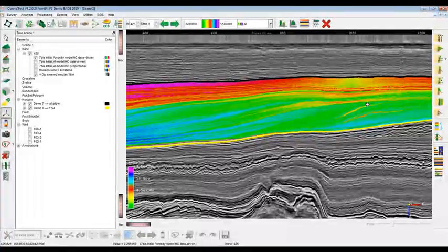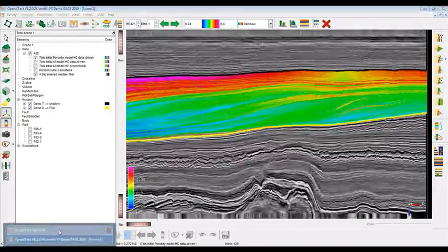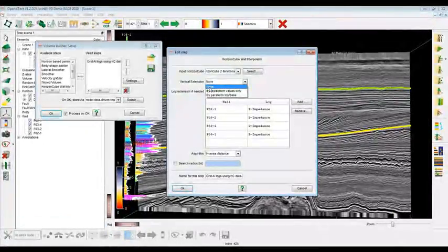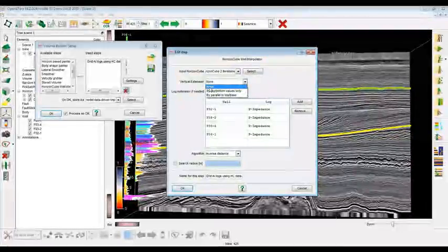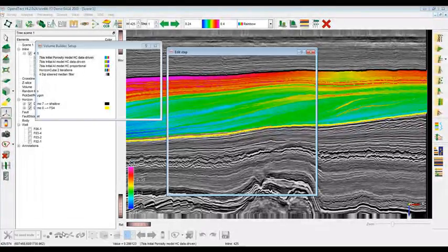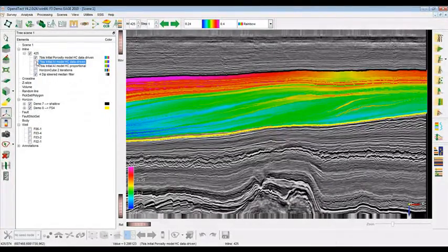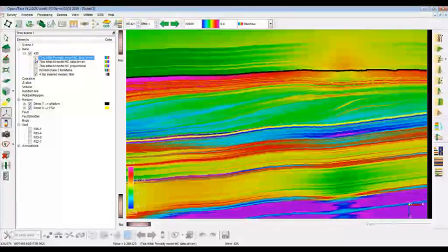Actually, these gridding steps are to be found here during gridding. You may want to either do no vertical extension of the gridded volume, in which case you'll get a HorizonCube like this, bounded by the HorizonCube geometry, or you may want to grid the data parallel to the top and base horizon, in which case you'll receive a volume where you have data everywhere, like in this example.